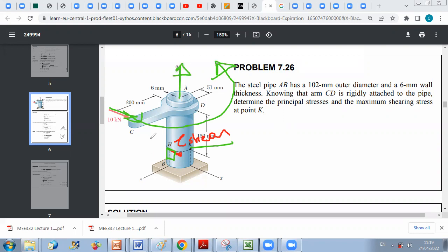Okay, so now from the torsional effect, the shear at H resulting from this torsion will be along, and if you do this with your hand, you can see that this torsional moment will lead to a shear stress distribution at H in the section. Anyway, at H you will also have shear like this, because this is along the rotation created by torsion.